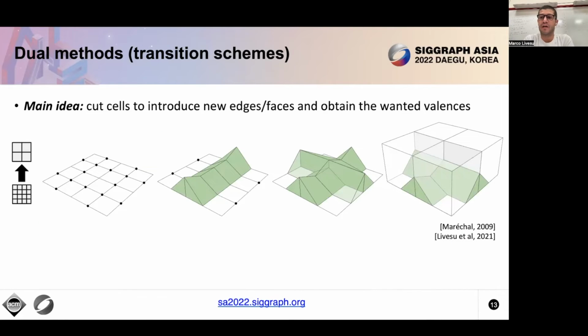If we take a look at how this extends to 3D, here is a depiction of the transitions. Here we are essentially going vertically from a 4x4 grid to a 2x2. And these are the hanging nodes, these black dots. And the way to suppress them is, first of all, to insert these prismatic elements, this chain here, and then another chain that essentially crosses the first one orthogonally, passing on top of it.